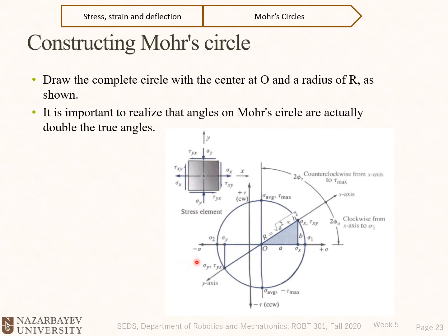Okay, so again, the Mohr circle is based on the sigma x prime, tau x prime y prime functions. It doesn't give us anything more than that, but it's just a very visual method to calculate formulas and find principal stresses and coordinate systems.